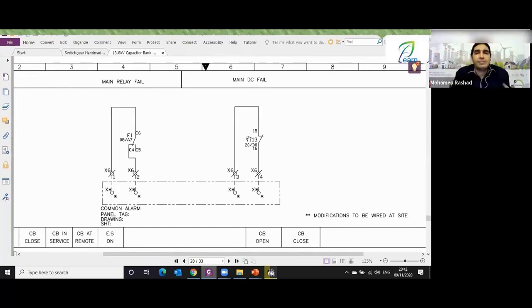All right, the relay itself is off. How does it understand? Yes, in this situation, when you have it on the relay itself, which is originally the one that sends the alarms to the SCADA, in this case, what do you do? You take this contact, not send it to the relay, and you send it here to a panel in your control room.